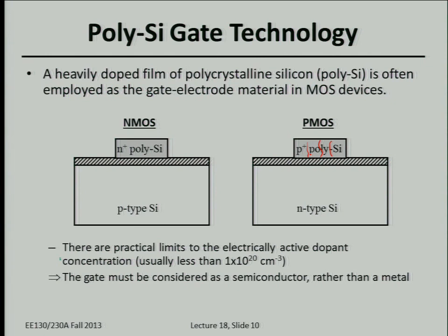During the fabrication process, a lot of the dopants in the polycrystalline silicon actually segregate to the grain boundaries, so they're not sitting in a normal lattice site with 4 nearest neighbors, and they don't actually act as dopants. The number of dopants could be very high, but the number of active dopants contributing carriers is typically quite low, depending on the polycrystalline defect density.